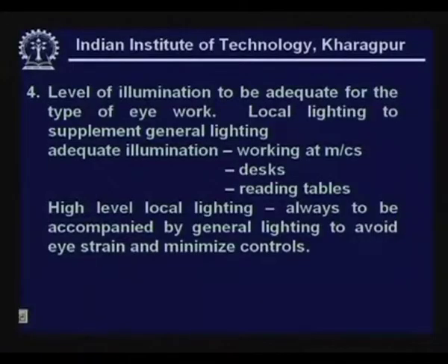If you are just watching a film with visuals, there may not be requirement of large illumination. On the other hand, if you had to read fine print, or one has to work at assembly line trying to assemble precision parts, there is a need for more intense illumination. So, local lighting is invariably a high level, and as already told, is always to be accompanied by general lighting.